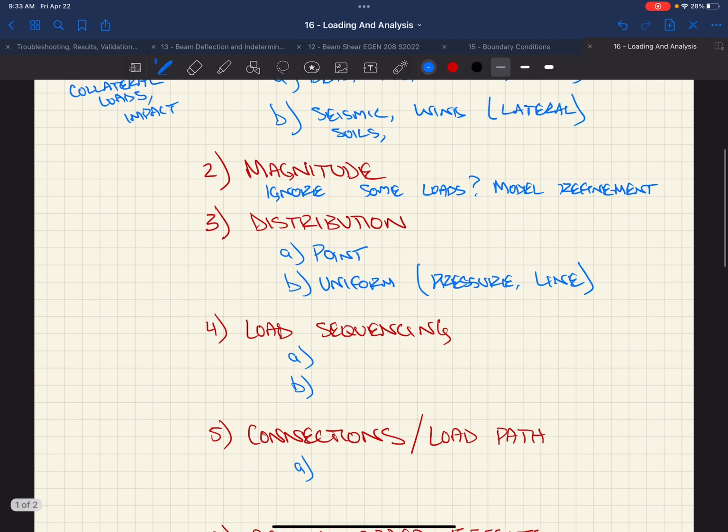Why would you not feel good about just turning it into a line load and putting it on there? If I was interested in, say, a shear wall on the outside of the building, and I wanted to incorporate the fact that there's out of plane loading on it, like Cobleigh Hall has big shear walls at the stairwells, right? Some of those walls are taking direct wind pressure, and they need to carry that while maybe getting a wind load the other way, where they have in-plane forces acting on them. Right, so you put that as wind pressure on the shear wall. So then, yeah, you could put it as a wind pressure on the edges of the shear wall. You do sometimes account for the lateral stiffness in the out of plane direction of shear walls.